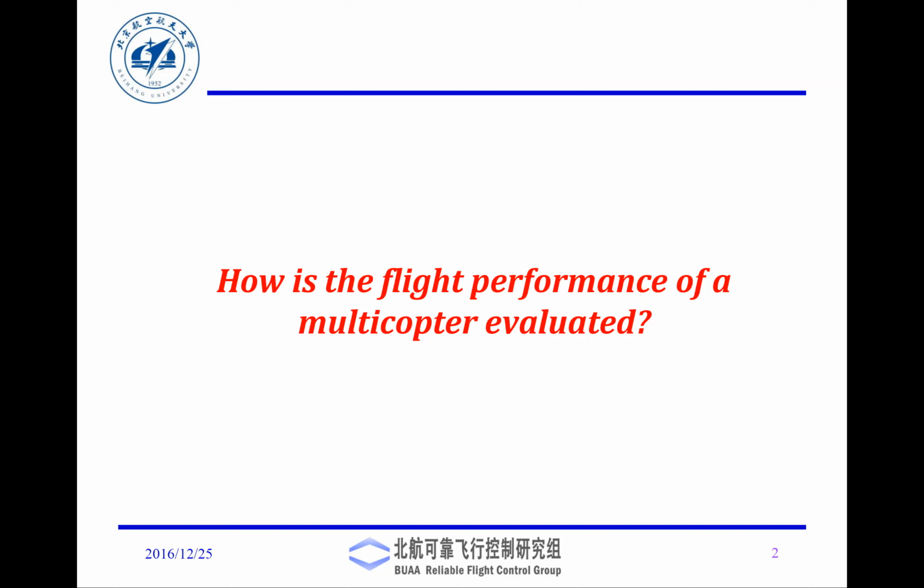You would also notice that every motor has something called the kV rating. kV is a factor that relates voltage to RPM. For example, this motor has 1000 kV, which means if I supply 1 volt to it, it will rotate at 1000 RPM. Usually quadcopters are powered with 12, 24, 36 volts. So you will notice that this motor is going to rotate at very, very high speed.